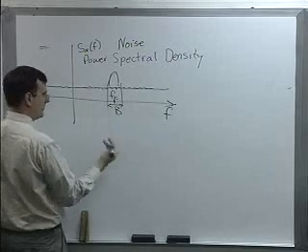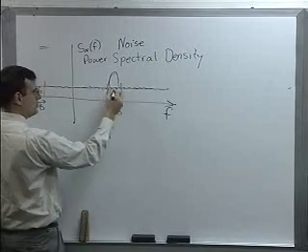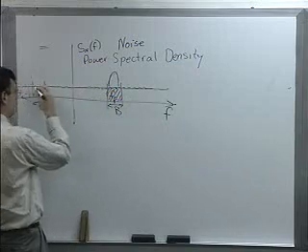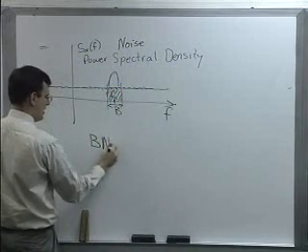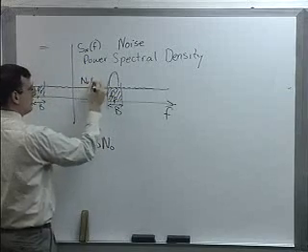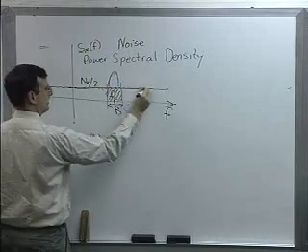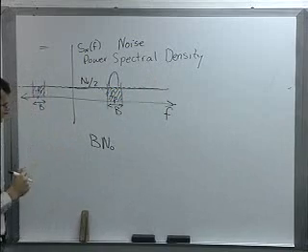So what we typically do to figure out exactly how much noise power is in there, we said last time that we used the equation B N naught, where N naught over 2 is the level of the power spectral density noise metric.